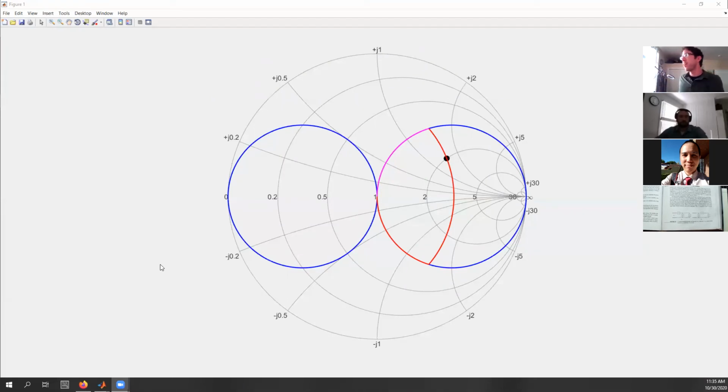frequency stuff. This lumped element matching is really only viable for frequencies below a gigahertz or so. When you start getting really, really high, you have to use more stub matching. We'll talk about that Monday, but this is a great stepping stone into that, right? This is a straightforward idea because it has a nice foundation in circuit theory, and the same ideas are going to apply when we do stub matching, which is a little bit more practical at higher frequencies.